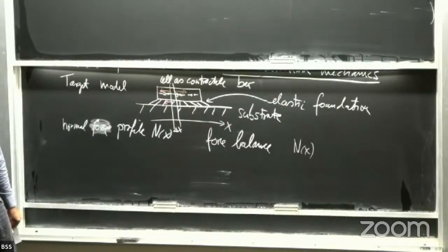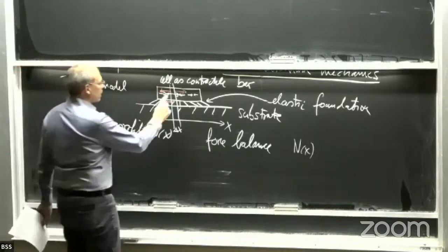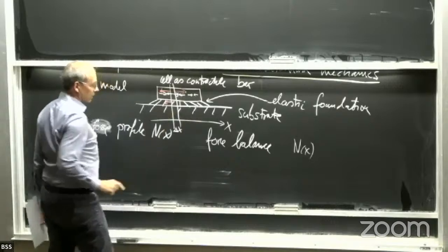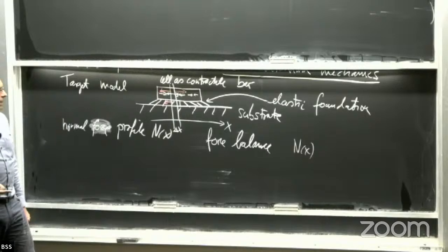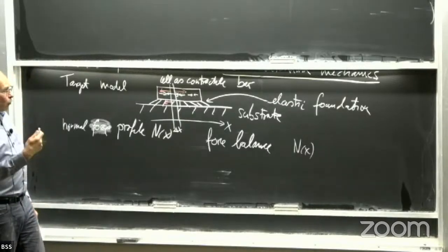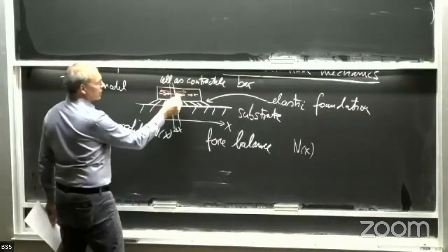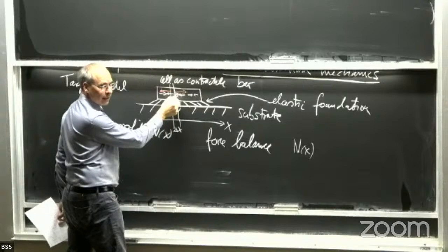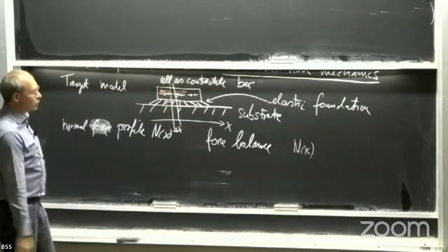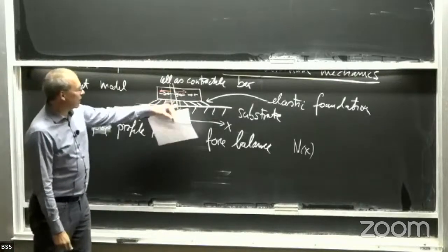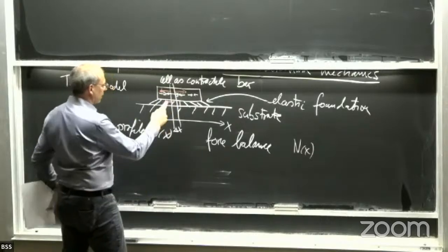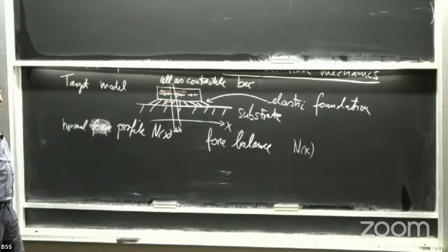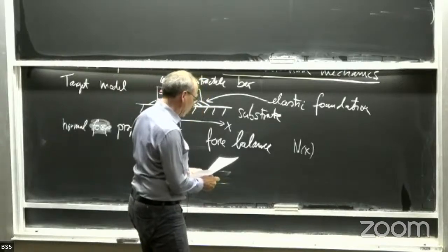What might look a little bit strange to you, okay, is that this here is the normal force. It points in two different directions, okay? But the reason is that we basically define it normal to a surface, and this normal changes its direction as I go from the left side to the right side, okay? So you have to get used to it. It's a matter of convention in some sense, okay? But we write positive numbers for the force, and we consider two forces which pull against each other, okay? So we basically consider these forces working against each other.